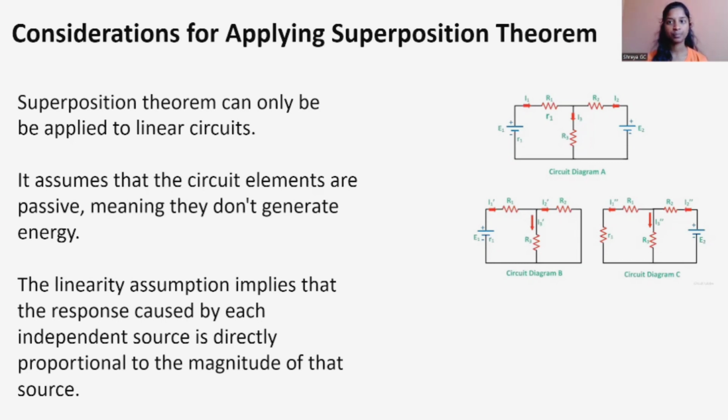Considerations for applying superposition theorem. Superposition theorem can only be applied to linear circuits. It assumes that the circuit elements are passive, meaning they don't generate energy. The linearity assumption implies that the response caused by each independent source is directly proportional to the magnitude of the source.